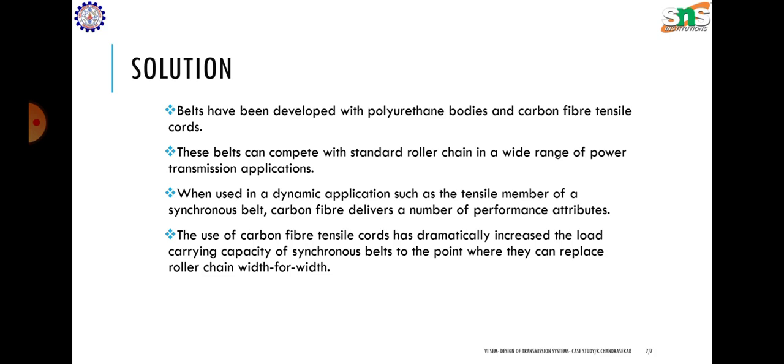If we use the gear train, then more complications occur. We need to fix more gears to transmit the power, and if one gear breaks down, then we need to shut down the total unit and replace it, and it takes so much time. Gear drives are used for transmitting power for a shorter distance only.